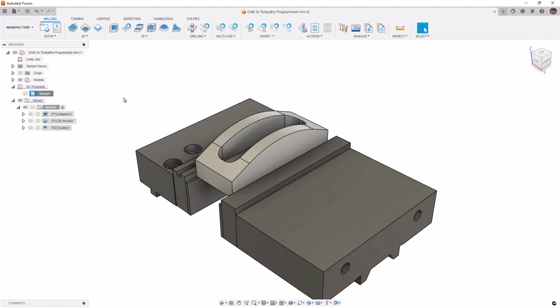At this point, we've taken a look at all the steps in the process of setting up, programming, and validating our CNC programs. Make sure that you spend enough time playing around with different models, generating various toolpaths, identifying any problems in simulation, and creating setup sheets and NC programs so that way you can take them to a physical machine and begin machining actual parts. Make sure that after you're done that you do have everything saved before you move on to any next steps.